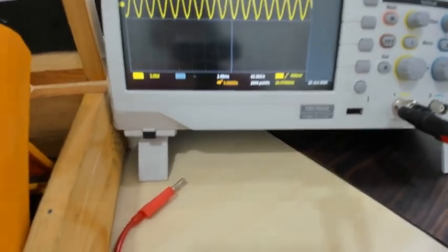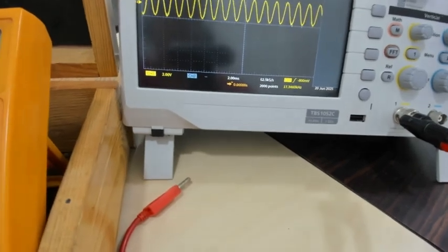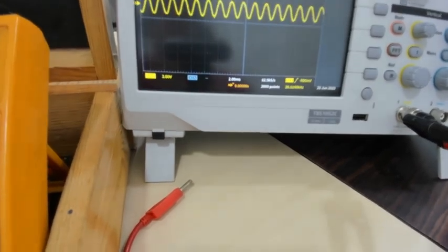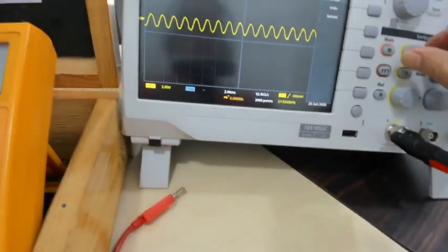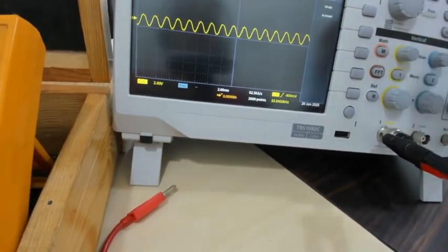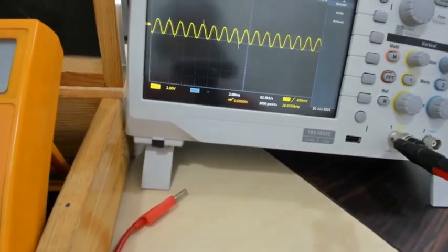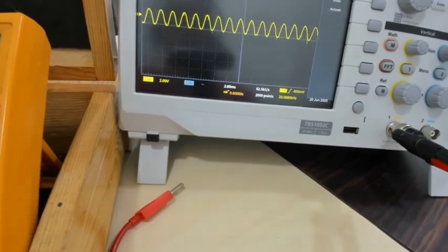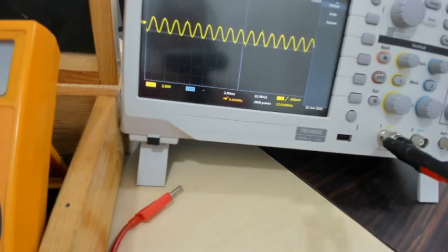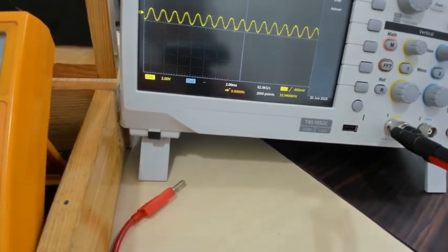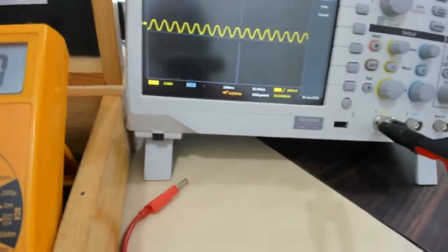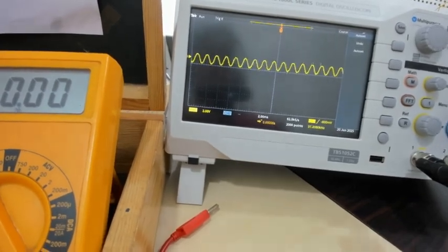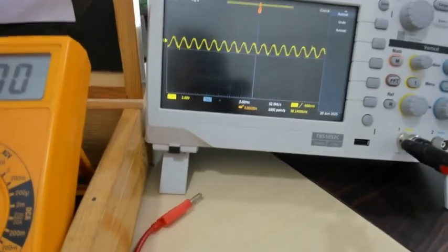Now if you are going to change the amplitude of the signal, then it is going to affect its output also. See. So this is how it is changing. Correct? So this is the perfectly demodulated output, almost the same that we have applied here. If you are going to change the frequency also, then it is going to affect this. See, this is the perfectly demodulated output. So if you match the frequency of the PLL with the carrier, then only you will be able to detect the modulating signal perfectly. Otherwise you will be getting distortions. So I hope this modulation and demodulation part is clear.